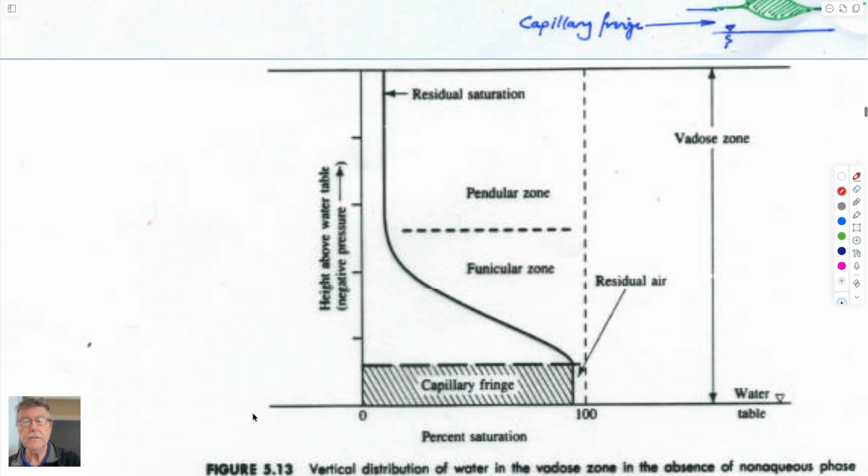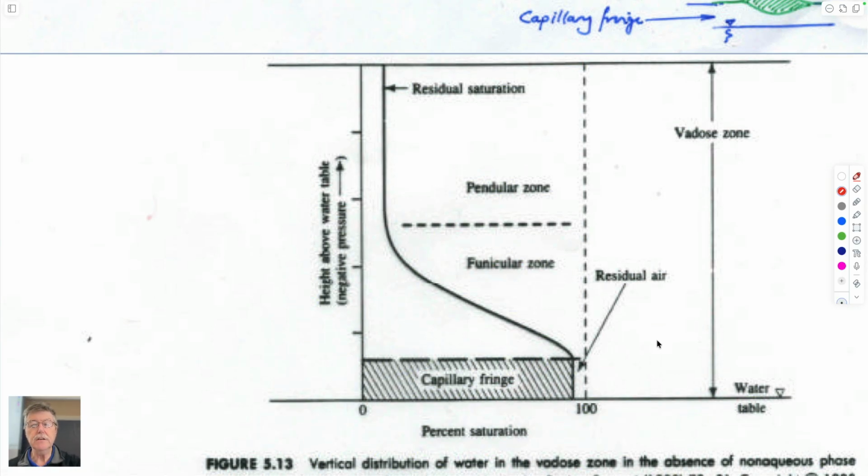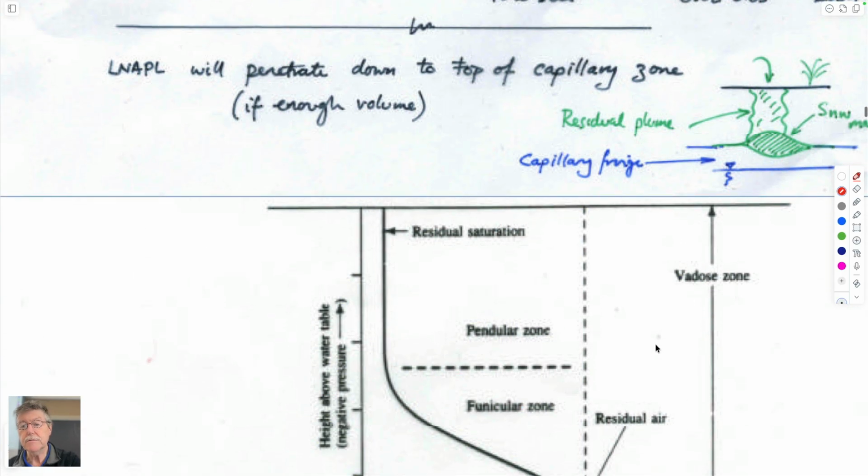And so if we look, first of all, at the capillary pressure versus saturation relationships, what we're trying to represent is this behavior. We've had these cartoons before. These cartoons for us have had a water table where the water pressure is atmospheric. Above it, the tension saturated zone gives this zone 100% almost saturating the porous medium, but at liquid pressures which are less than 0, negative.